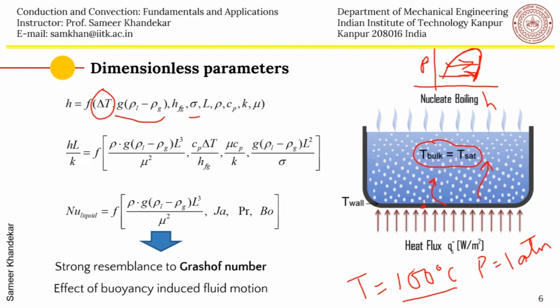There is a typical length scale. The length scale can be the size of the bubble, for example. The densities of liquid and vapor play a role. The specific heat of the liquid plays a role. The thermal conductivity of the liquid plays a role. And the viscosity of the liquid, because the bubble has to now travel upwards. It has to first grow, it has to push the liquid away and then grow, and then leave the surface and then travel upwards. So there is friction, which is in the form of the viscosity of the liquid and the vapor.